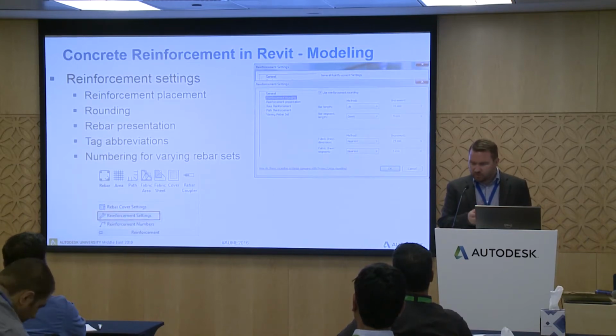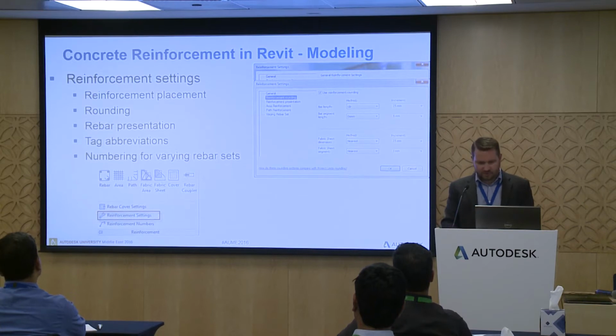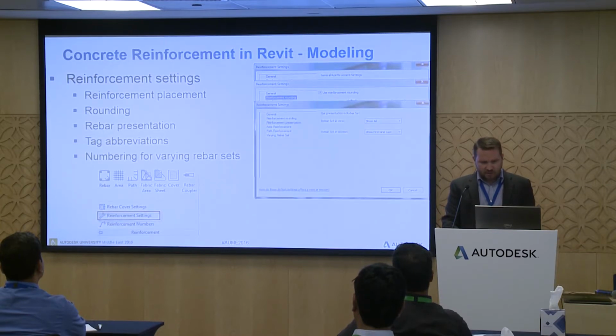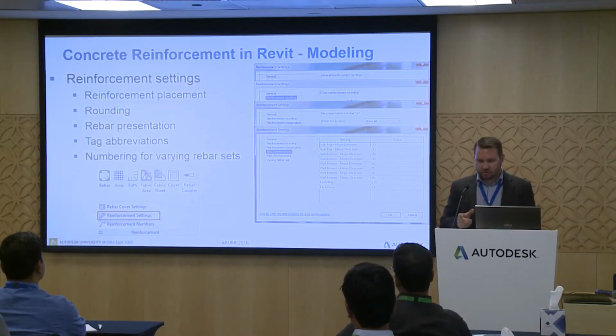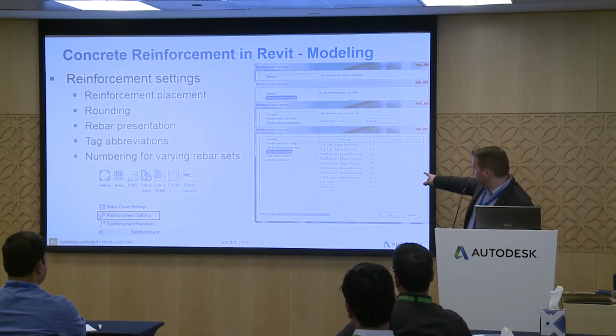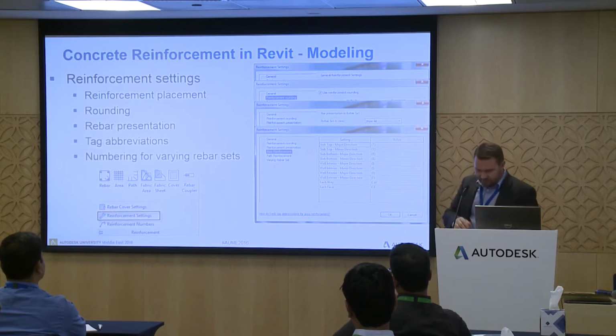You can round the value of the reinforcement, rebar or sheet fabric. And you can choose whether by default you want the tag to show all reinforcement tags or not. You can also choose in settings the area of reinforcement, the value and the settings.